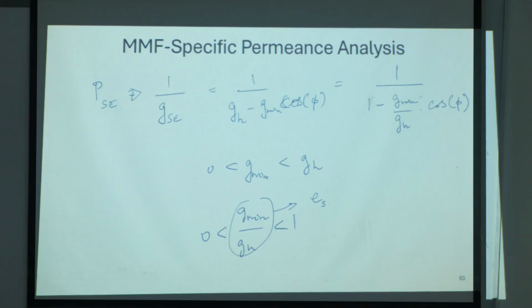So in the example values I have chosen, when we have a 5 mm minimum gap for a 10 mm uniform gap machine, the severity is 50%. 50% is very high. When the severity percentage is less than 10, it is very small. When it is above 10, we are entering a faulty condition and we have to diagnose it. 50% is huge, so we have to immediately stop the motor, diagnose it and fix it.